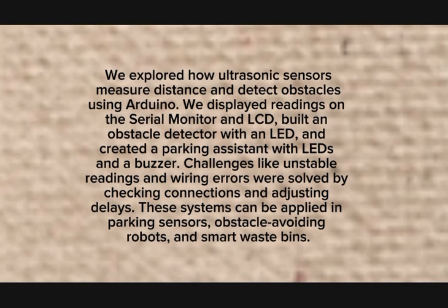We displayed readings on the serial monitor and LCD, built an obstacle detector with an LED, and created a parking assistant with LEDs and a buzzer. Challenges like unstable readings and wiring errors were solved by checking connections and adjusting delays. These systems can be applied in parking sensors, obstacle avoiding robots, and smart waste bins.